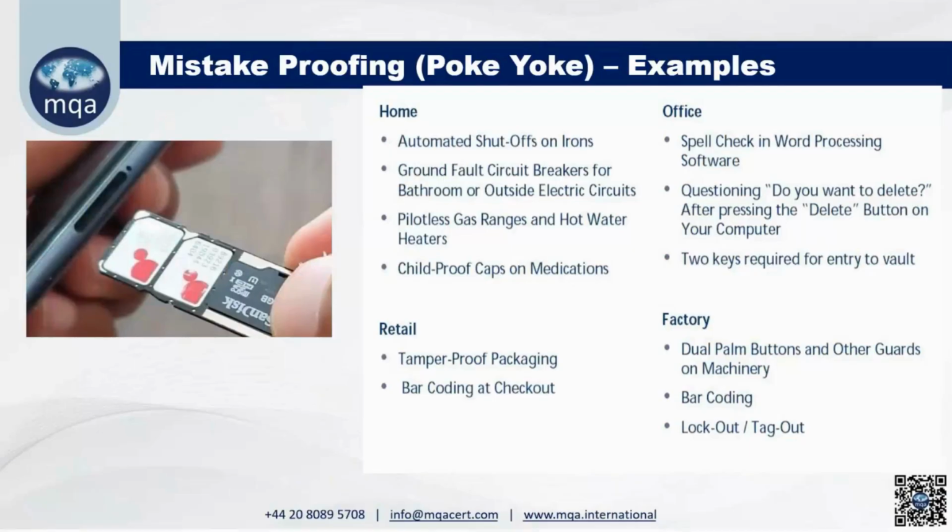One more example was in a punching operation. You know there are foot operated switches and hand operated switches. There was one Poka-Yoke where the controls were two-way. You have to switch on with the hand and also switch on with the foot. So this is also Poka-Yoke. Without simultaneous switching on of hand and foot, the machine will not start.